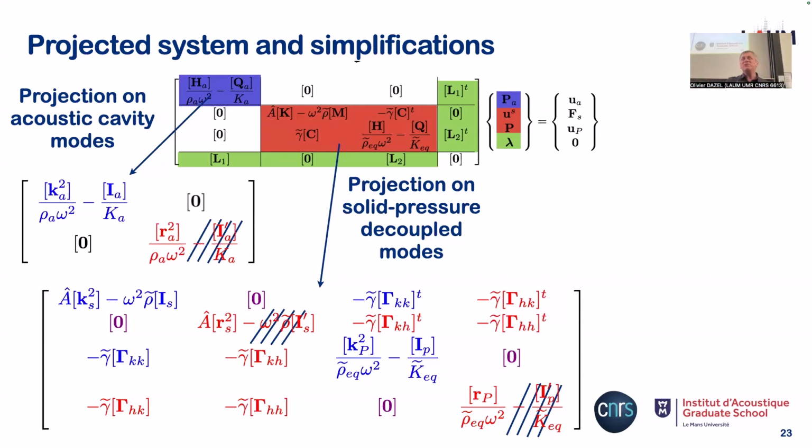So what we are doing is something based on the fact that in the physics there is a dissimilarity between the fluid and the solid phase. As I presented before, the fluid phase does not have the strength to excite the solid phase too much. So we will neglect this term, corresponding to the excitation of the solid part by the fluid phase, or by the neglected modes of the fluid phase. We are doing this classical approximation to suppress that term, and I also neglect this one. We have tested that several times on the full order model, and this is a very reasonable assumption. And when we are at that step, with all I presented, everything that I will derive now will be just exact.